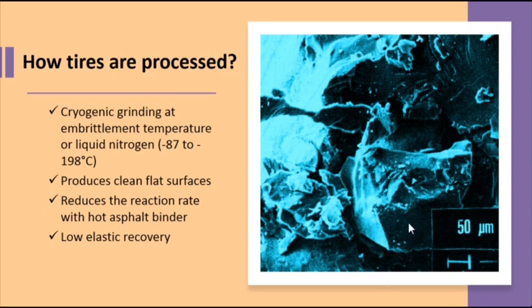In comparison, ambient granulated crumb rubber results in a higher binder viscosity than any of the modified binders produced with an equal amount of cryogenic crumb rubber. This is possible due to the very high surface area and irregular shape of the ambient rubber particles, which permits a faster reaction with the asphalt binder compared to the cryogenic rubber. The above explanation demonstrates that the method used to manufacture crumb rubber has an influence on the extent to which the properties are enhanced.